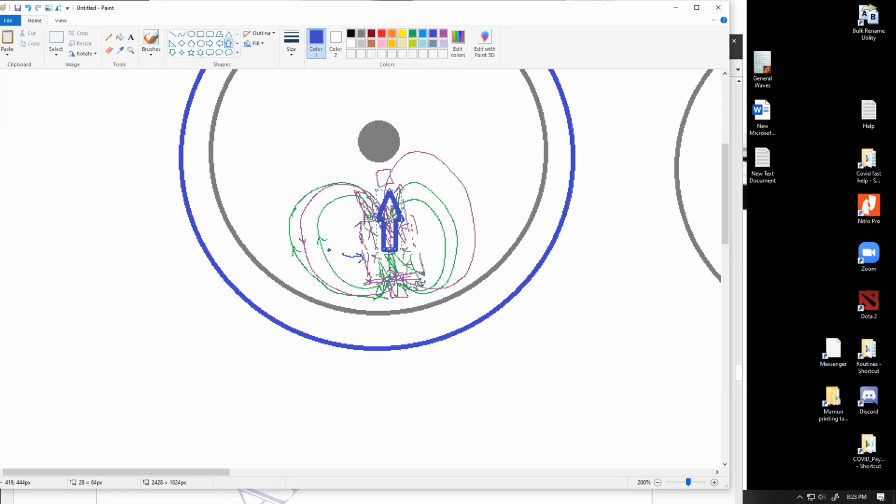Now, if you use this conventional current, and try to find out the direction of the force that this conventional current will produce onto the disk, what would be the direction of that force? What is the direction of the force that this current will produce onto this disk? Sir, downward. No. Aim your index finger into the screen, align your middle finger towards the center, and extend up your thumb. Where does your thumb aim? Sir, to the left. To the left. Exactly, to the left. So let me draw that with, let's say, red.